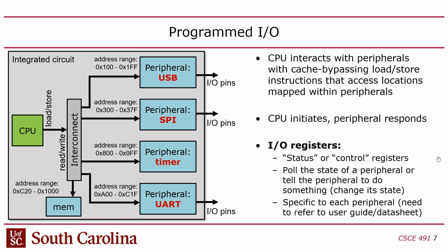They'll have a lot of unique addresses associated with them. Some of them will just have one, right? Some of these peripherals you can get away with one, like literally just one register. Other ones have a ton of registers. Some of them have a lot of registers because they have an internal buffer. You can actually write data into these addresses to buffer inside of here, and then later on they'll send that data out through a serial interface or something. Does it make sense? So it just all depends on the peripheral.